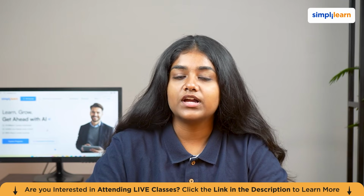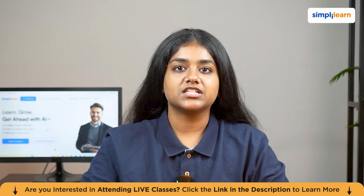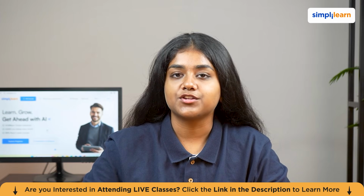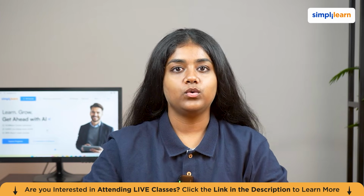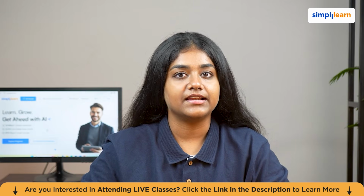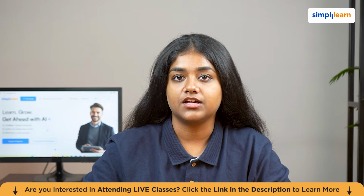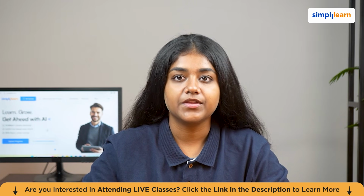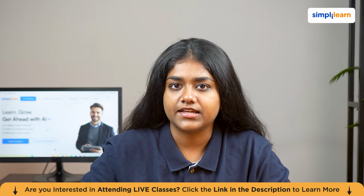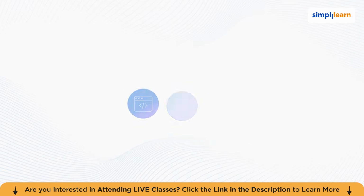In this module, we covered the traditional average and range method for calculating gauge R&R, a transparent and calculable approach that partitions total measurement variation into equipment variation and appraiser variation. We explored how percentage GRR is calculated and interpreted against the AIAG acceptance guidelines: under 10% acceptable, 10 to 30% marginal, and over 30% unacceptable, and how the number of distinct categories tells you whether a gauge can meaningfully distinguish between the parts.